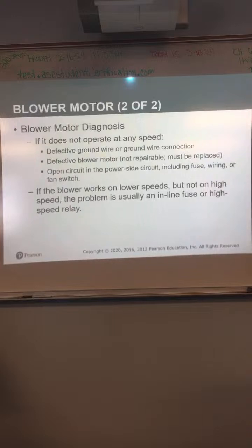Diagnosis of the blower motor. If it does not operate at any speed, meaning you got no blower at all, you have a bad ground wire, a bad power wire, or a bad motor itself. And in the power circuit, obviously that can include a fuse, wiring, something like that. If the blower motor works on low speed but not on high, usually an inline fuse or high-speed relay.